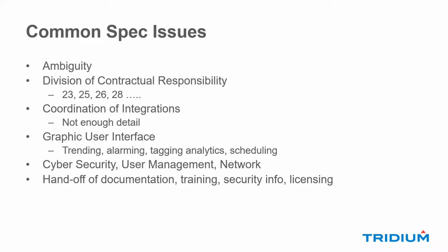If I'm going to connect to a chiller, am I going to do it with some hardwire? Am I going to do it with a BACnet interface, a Modbus interface? How am I going to connect? We want to make sure we understand exactly how we're going to do that, because it's very important when it comes to getting accurate projects and accurate pricing.